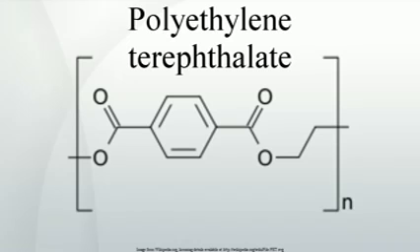carpet yarn, engineering plastic, filaments, non-woven, packaging stripes, staple fiber. Choosing the repelletizing way means having an additional conversion process that is, at the one side, energy-intensive and cost-consuming, and causes thermal destruction. At the other side, the pelletizing step is providing the following advantages: intensive melt filtration, intermediate quality control, modification by additives, product selection and separation by quality, processing flexibility increased, quality uniformization.